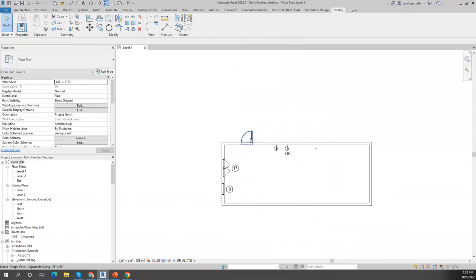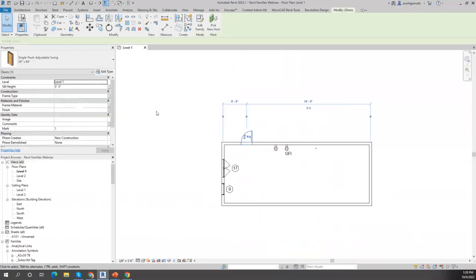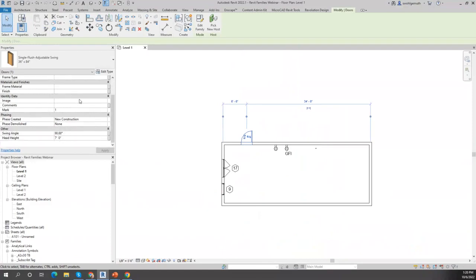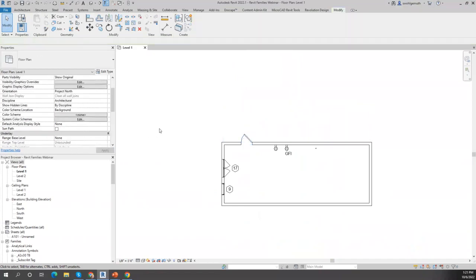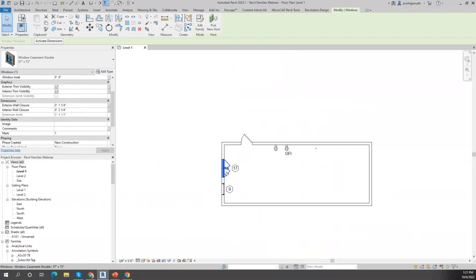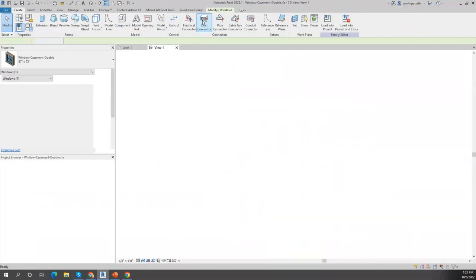So that is a very simple door. What I made extra for it is that it has an element parameter, which is the swing angle, that allows me to change the angle in which it opens. There are architectural firms that like to do that to give less relevance to certain doors, or to show existing doors. Now, those parameters and those reference planes can become very complex. Let me open up the door family. This is a window family, sorry.